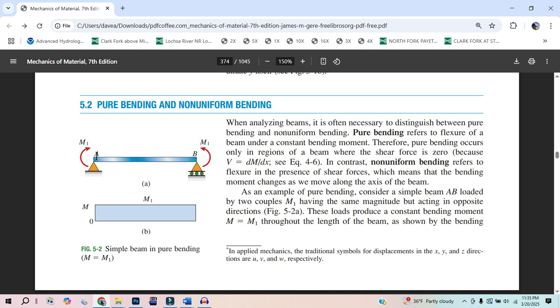You know what I mean? It's not going to be pure bending from there to there, where the applied loads are applied. But I just want to say, this is very useful to me, and I kind of just came up with it. It's just that aha moment this month, like, hey, a pure moment like this, if you see a curved line and that's indicating a moment, it doesn't exist. You know what I mean? You can't apply a moment at a point.